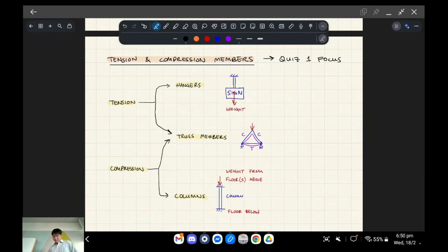So tension and compression are just types of loading. For example, here I've got a bit of wood, a solid material. If I'm pulling on it, that's tension. I'm pulling in both directions, it's straightening out. Compression is when I'm pushing it together like that, and what you see is it starts to buckle. I'm going to talk about that very briefly, but you're going to see this in compression members which are very slender, which means very skinny and long.